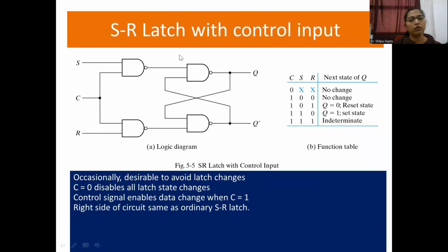Okay. Now, as we have already discussed, if we need to make a latch a flip-flop, then we have to add the clock signal, and this clock signal basically provides the timing for this particular latch. Timing signals are the clock signals. So if we want to put a clock signal to this, we have to install a set of more gates in front of the input so as to get the output.